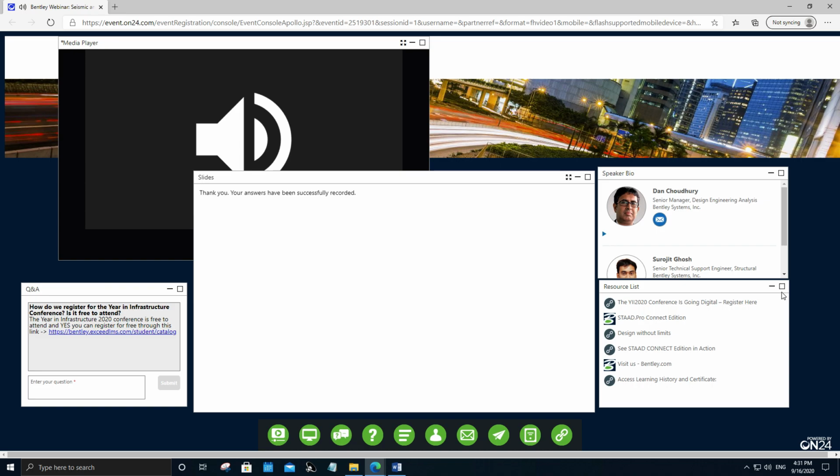On the other hand, if you do want to consider the mass participation in the vertical direction, and the vertical direction is a stiff direction, then one thing that you could check is whether the frequency of the vertical modes is over 20 hertz. That would mean that it's basically a static mode.